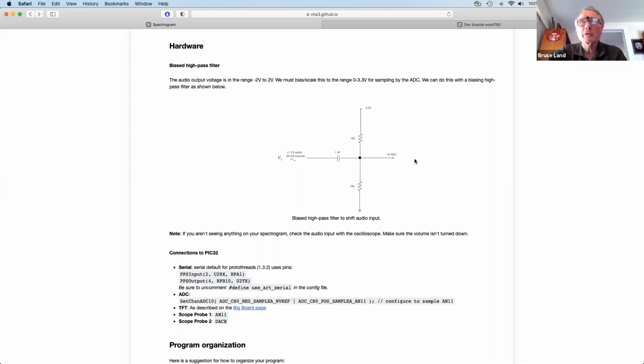Well, remember, you're only looking at the spectrum. Now, if there's clipping, you're going to have a lot more high frequency energy because the waves look more square. Exactly. And so you're going to get the spectrum of a square wave out. If you put a sine wave in, you'll get a spectrum of a square wave out. That tells you it's clipping. Thank you.